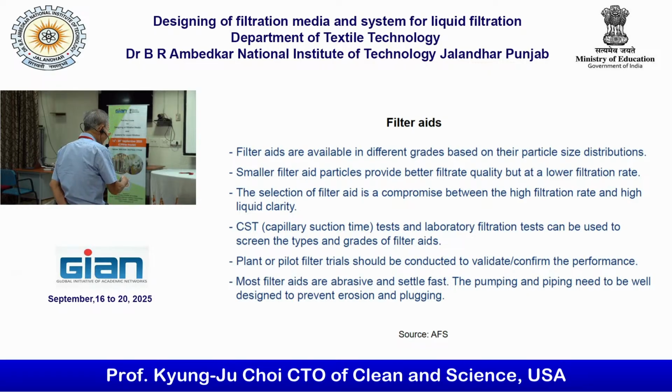This is the equipment, capillary suction time. This is really simple equipment using the filter paper and slurry. You put some slurry into it, and then check the speed of soaking through it. So you can actually estimate filtration rate that way.